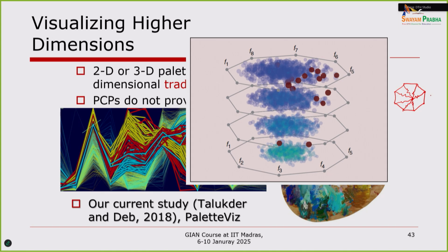The spring stiffness is inversely proportional to your F. So if this is 1, 2, 3, this one is inversely proportional to F1, inversely proportional to F2. So if you have a very small F, you have a very large stiffness. It's a very stiff spring. If you have a very large F, that means not good, you have a soft spring. So now you apply physics and find out the equilibrium point when each of the springs are in equilibrium with the forces. What is the location? And this will always be inside, right? What is the location of that? So that kind of tells you an idea of these 8 dimensions, what it's doing to that puck in the middle. So these points you see, these are those locations in this octagon.